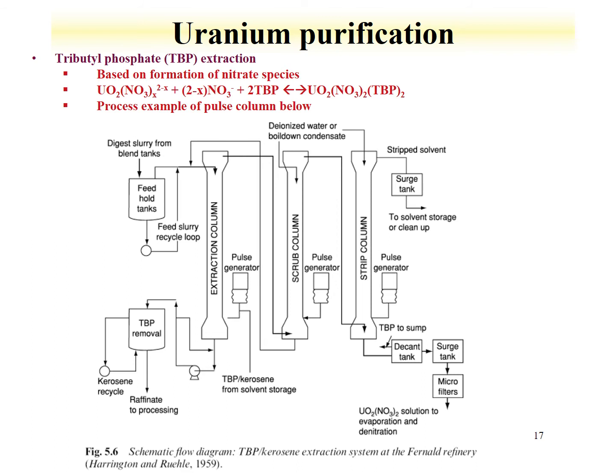Here's an example of uranium purification by solvent extraction, similar to the tributyl phosphate extraction that was done in the laboratory, except in this system a pulse column is used. For instance, we would have a feed tank that would hold the solution containing the uranium, and a column with tributyl phosphate. The aqueous phase would be added to the pulse column, and the drops migrate down.